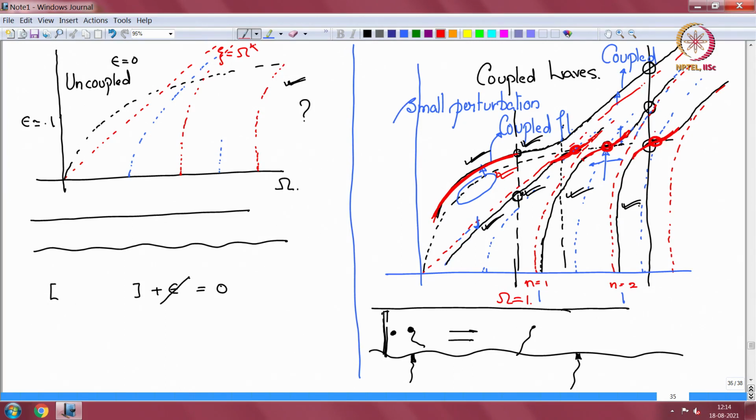So, the solution we have derived, xi is equal to omega to the power half and some correction, epsilon by 4 etc., is represented pictorially by these short red portions I have. So, that means this original flexural wave which I now completely show in red, in localized regions is modified to this.